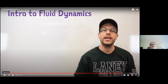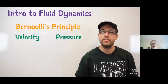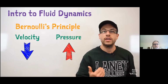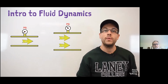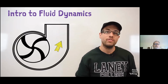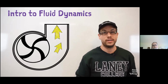This is where a guy by the name of Daniel Bernoulli comes in. He discovered 300 years ago that there's an inverse relationship between a fluid's velocity, or speed, and its pressure. Meaning that if the velocity goes up, then the pressure comes down. And if the velocity goes down, then the pressure automatically goes up. So as the fluid is slowing down in the ever-expanding volute chamber, it's also picking up pressure. By the time the fluid reaches the discharge outlet, a great deal of its kinetic energy has been transformed into pressure energy. And I think that's a pretty amazing little trick.